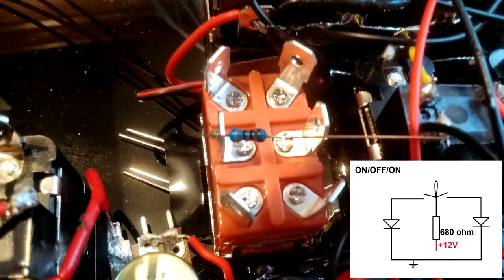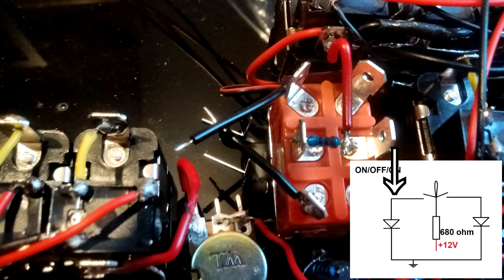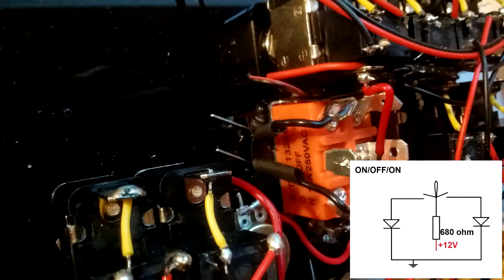The wiring diagram is quite the same as the one for the landing gear, except the two LEDs are the same, so we need one resistor. I've taken a plus 12 volts on the neighbor button that I connect to this resistor. I've soldered two black wires on the other legs of the button, and I've bent up the two anodes. I've put some heat shrinkable sleeves and I've soldered the two black wires on the two anodes.